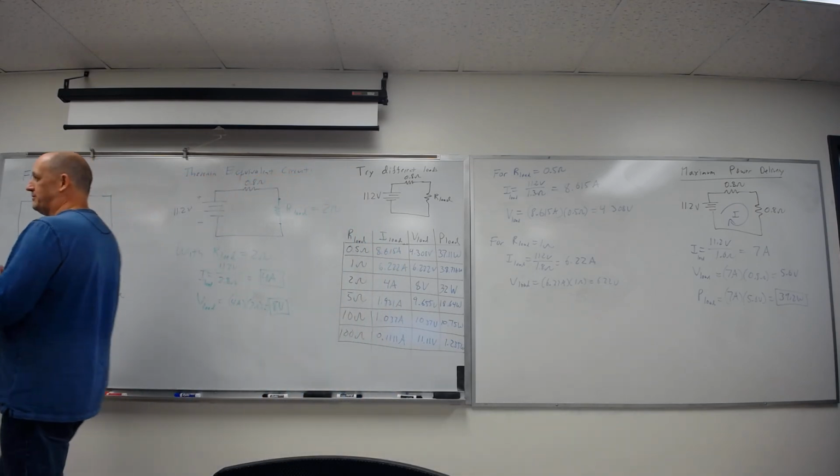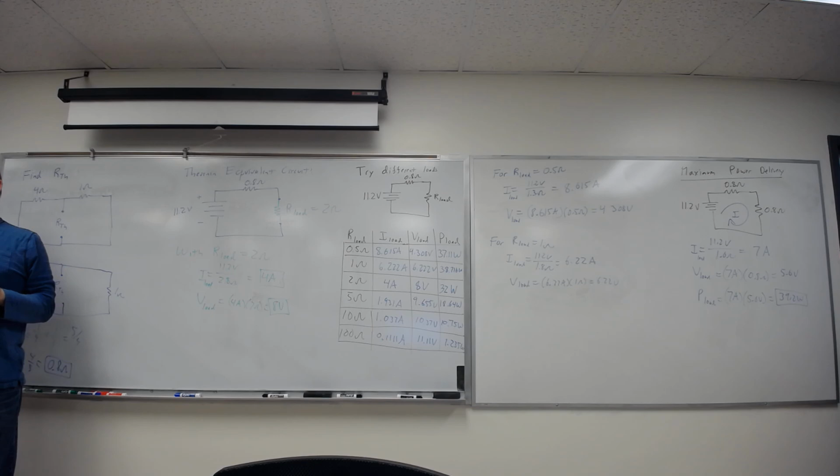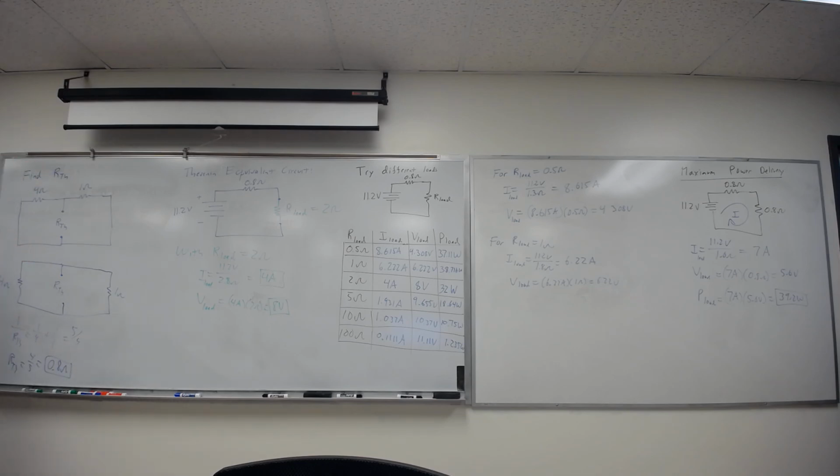Okay, so we know Thevenin equivalent. Lots of homework this week, and a whole lab doing Thevenin equivalent. When I get to lab, I can build that exact circuit, then remove the resistor and measure the voltage across it, and I have my Thevenin voltage. Leave that resistor out, remove both power supplies completely from the system, and then go in where they were connected and put shorts on there. Once the power supplies are disconnected, I can't emphasize that enough. Do not short them while they're connected. Then go back and measure the resistance across those two and get the equivalent resistance.